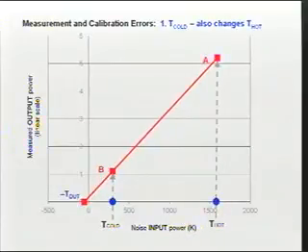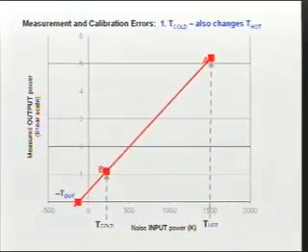And what happens then is that small error goes degree for degree. 6 Kelvin will give you 0.1 dB error in your noise figure result. Yeah, and that's a completely avoidable error. That error is almost in the category of user error, finger trouble.